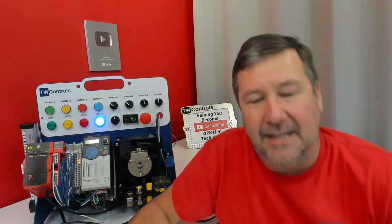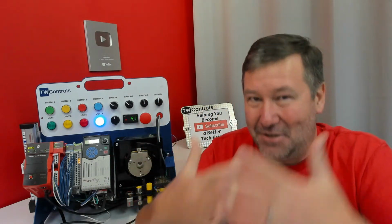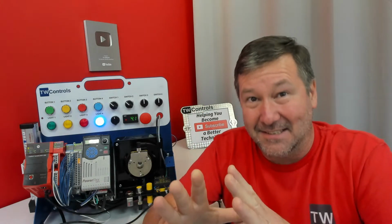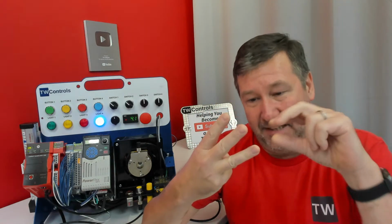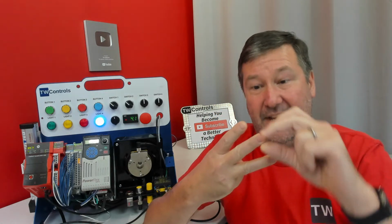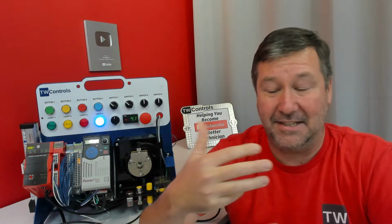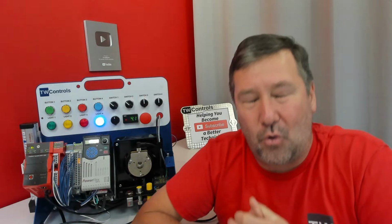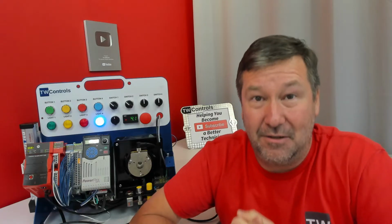Now I'm trying to ping 192.168.20.10. And here's where I usually have to stress, this is not a networking class. This is how do we get connected to our PLC when we're in front of it out in the plant. But for basic connections, the first three octets, and the octets are those groups of numbers, so an octet is a 192, another one is 168, another is 20, and the fourth one is 10 in our case. But those first three have to be the same. And incredibly important, that fourth one has to be unique.